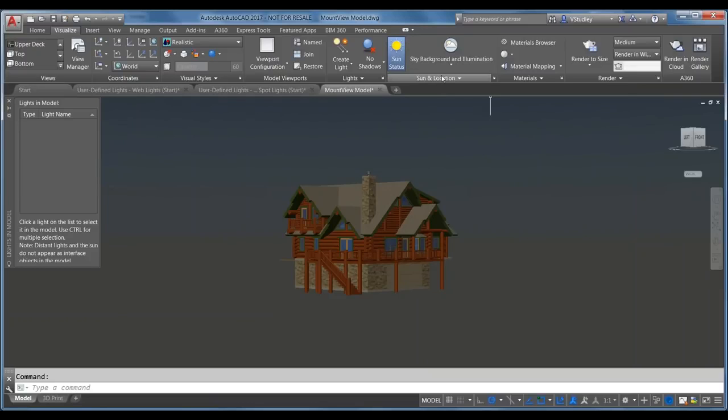So now I've done that. The next thing is to set your model in an accurate geographic location. I'm going to use our Boston office location as an example. You can use the geographic location tools within AutoCAD to set the location of your model and put it into those real coordinates so that the sunlight will be accurately emulated for the time and date that you designate.